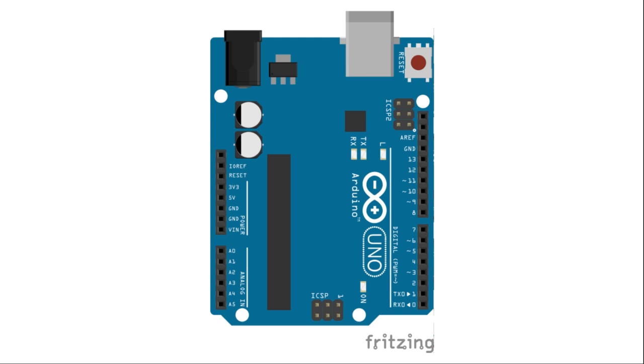Next we've got one more ground pin and the analog reference or AREF pin. It is an input pin. It allows us to set the high signal value. For example, we may want to set the high value to be 2 volts instead of 3.3 volts. It depends on the design of our circuit, but now you know there is an option to change the voltage level for the high value.